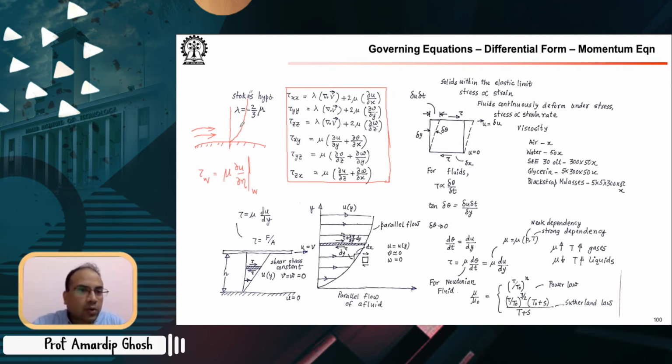Depending on whether you're looking at a laminar, transitional or turbulent boundary layer, the nature of the increase of thickness with Mach number and extent will change. But nonetheless, this is a case which we will call a parallel flow problem. Here you don't have a variation in the v component or w component of velocity.